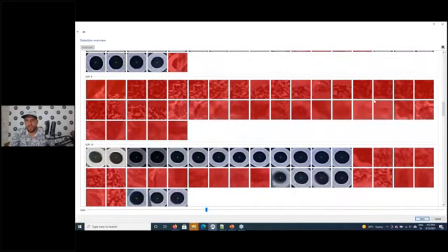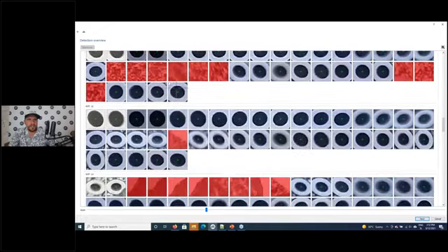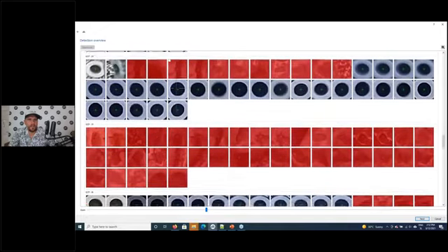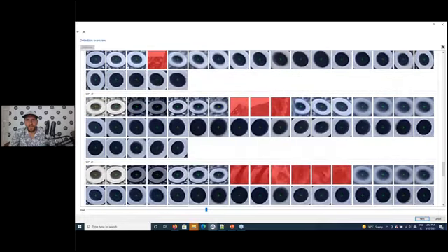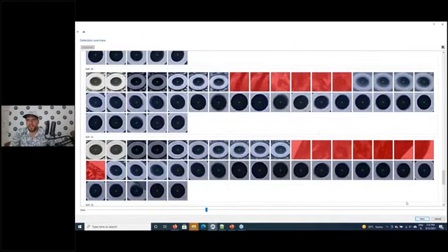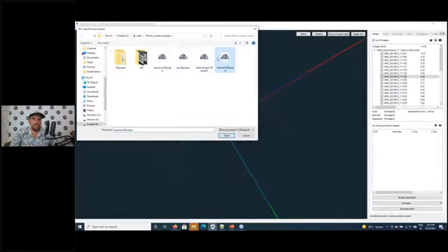So ground control point 9 is not visible on any photos. Same thing should happen to number 15. You would go through all of this, press next, and then like that, orientate your 3D model. So what I will do at this point, I'll just press cancel, and I will just load a project that's already orientated.